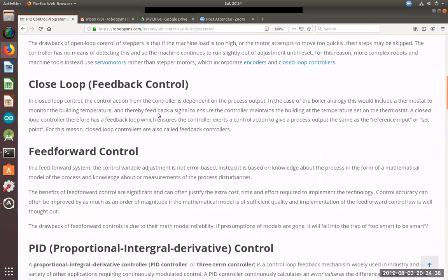Okay. So this proportional control is a typical feedback control, right? There's another kind of control called feed-forward control. What's the feed-forward control? You just mentioned you expect your robot will overshoot, right? Then what should you do? You just underturn a little bit, right? But the problem is how much underturn you're going to do. It depends on the friction of the robot and the speed of the robot. You don't know the value. You cannot calculate the value. Then what should you do? What should we do? Huh?